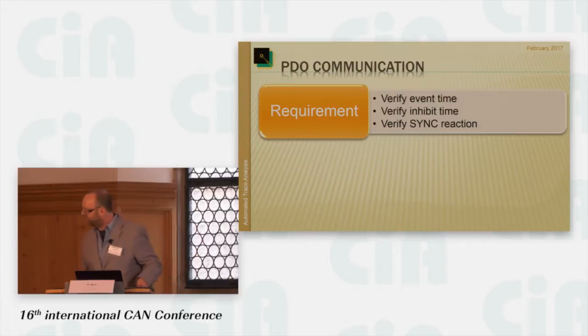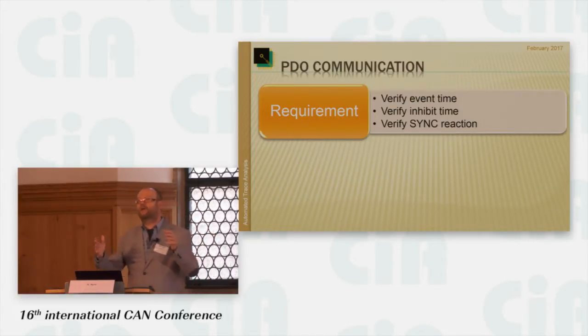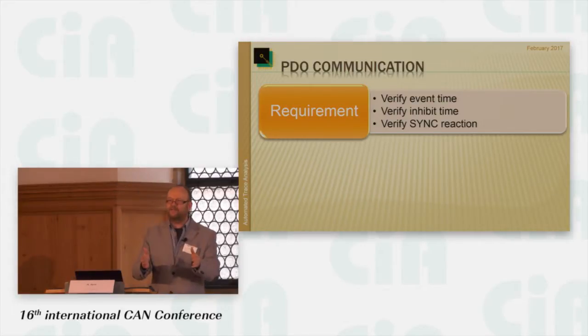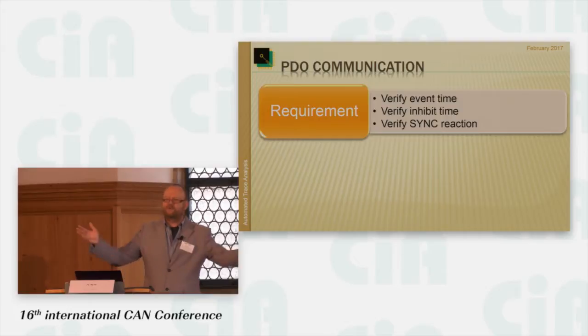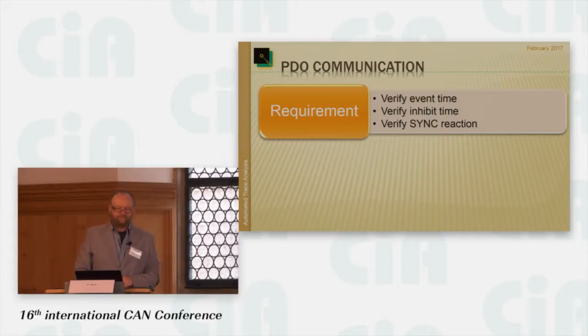And another fault we also found with this system is that for a segmented SDO transfer, where larger data is split into blocks, it would only fail depending on data size. So suddenly you had situations where if you do a device test alone, a standalone test, you only test a few sizes. You don't test all possible data sizes, right? But only in regular operation do you find those.